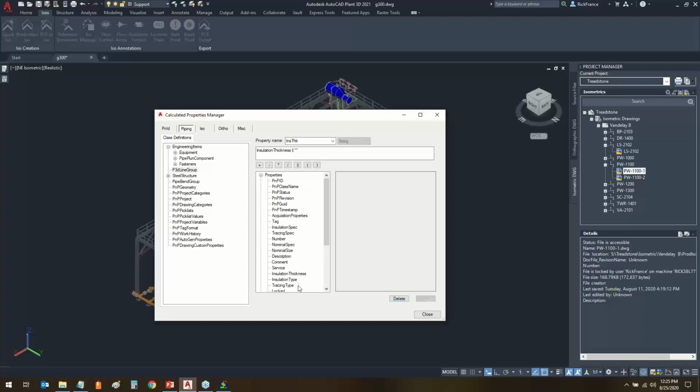And for like the P3D line group, I could, for instance, take the nominal size and multiply it by, to get alternate units, stuff like that, any type of thing I want to do. And then I have some functions here for substring, upper to lower string, and to number that I could also do. So you've got some different functions. I wish it would add some functions like if statements. That would be nice, but they don't right now.